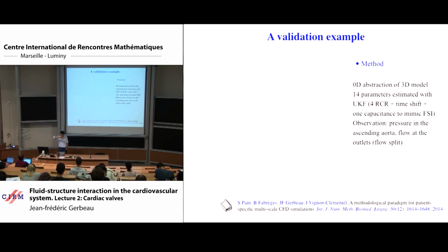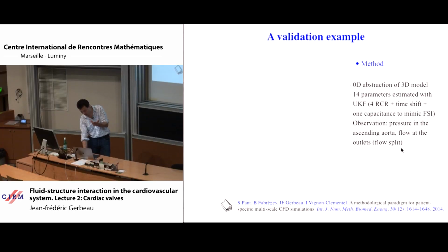So it was only fluid simulation, but we took into account fluid structure by introducing a sort of capacitance to mimic FSI. And so we used the 0D abstraction of the model, and we estimated 14 parameters. Okay, so it's a lot.